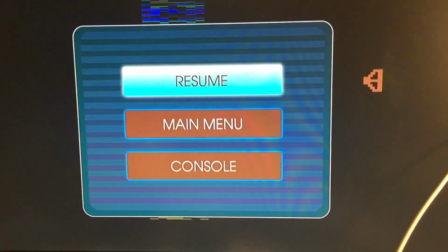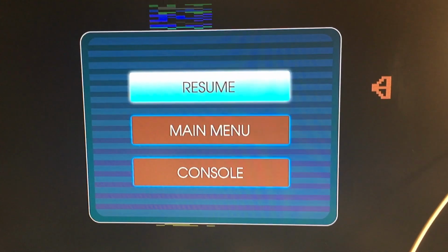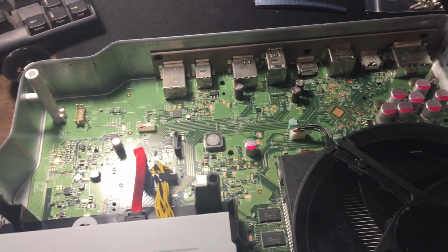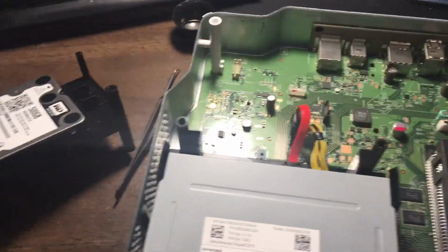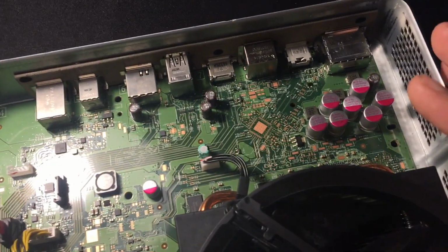At 1080p, it starts to act really weird. I've never seen anything like this before. I thought maybe it was the port. I replaced it, and it didn't change a thing. I was able to see the picture well enough to know the hard drive itself wasn't a problem anymore, but there was some sort of video output issue.